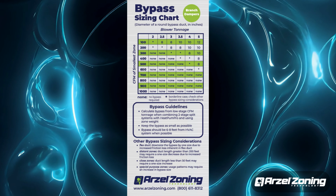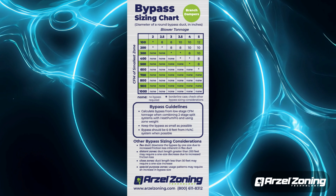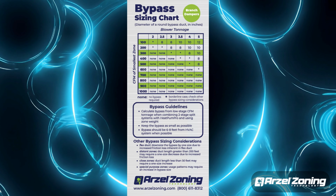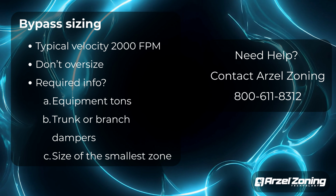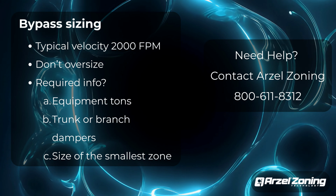Branch damper systems, the blower can build a nice static pressure throughout the system, and it just makes a more stable system. If you have a combination, like 50-50, err on the side of caution, just treat it like a trunk damper system. End of the day, if you have any questions on this at all, you can just call us. Here's what I got, here's what I designed, do you think I need a bypass or not?